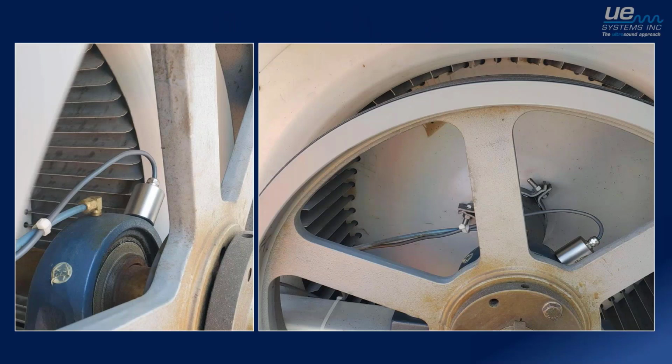So this is an example of an ultrasound sensor on a bearing. And in fact, you can see the remote lubrication line there as well. So it sits external to the bearing itself. What is great about ultrasound is it's very directional. And if you think about it, if you put your ear anywhere on this bearing, if it's at that point in its failure curve, you're going to hear it. So we don't have to be worried about different axes of measurement and movement and things like that.